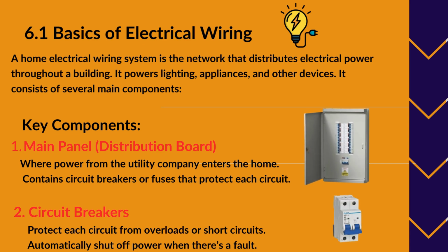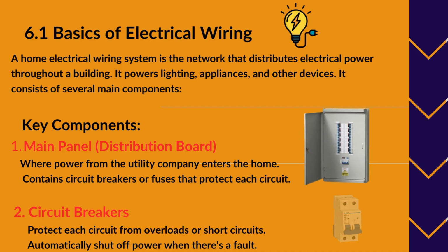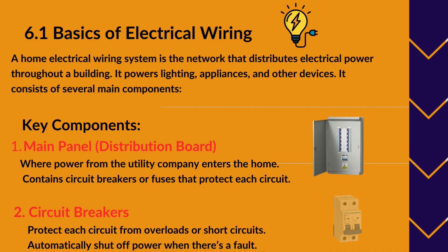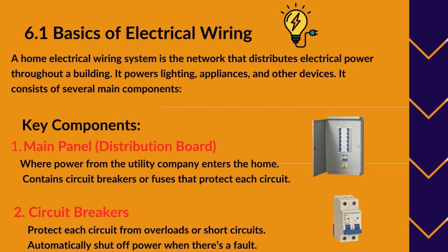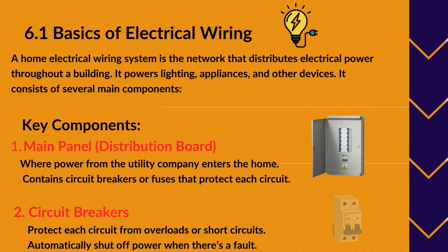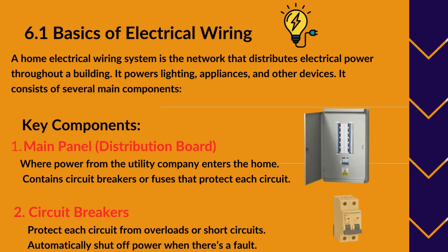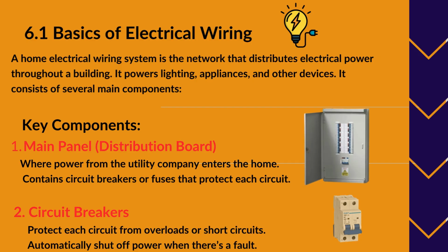It also consists of several main components. Number one, we'll talk about the DB, which is the distribution board, where the power is terminated. When you bring power from the main grid, some will use a changeover in Africa, where you can change between different sources of energy, either generator or so. But normally there's also the power cable from the grid straight to your DB. Then from your DB, you distribute to all your sockets and your switches in the home.